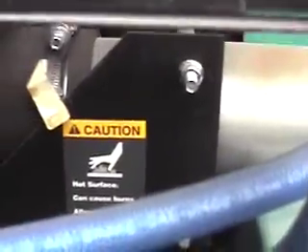So after the turbo, it goes through the air piece and comes back out. I have had people call me and say, I pulled these lines off and I don't have any coolant in them. We're down low on coolant, but I see coolant up in the radiator. I'm just like, okay, well, did you pull the silver pipes off or did you pull the black pipes off? Silver pipes have no coolant in them whatsoever. Okay?